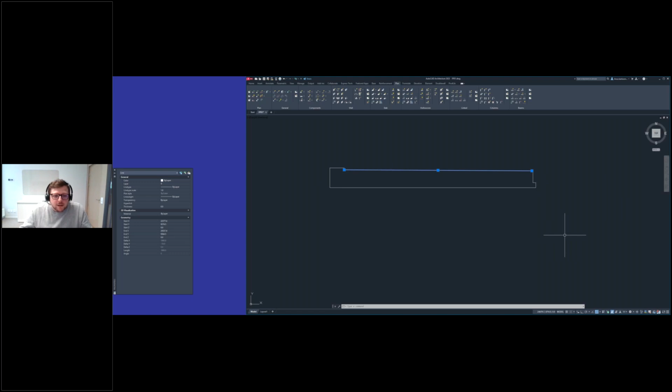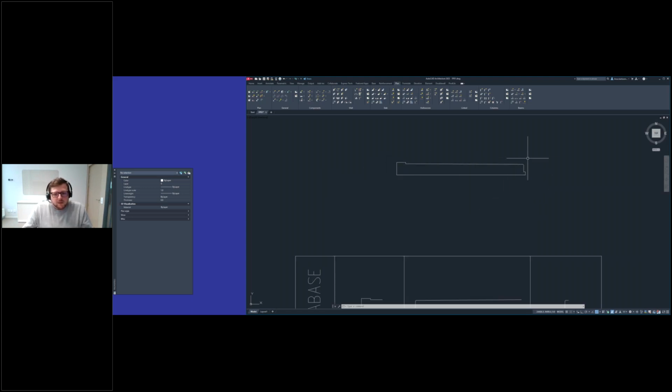To make sure that Impact knows that, we need to create individual end caps for each balcony type. For the same size, the depth or width, you can reuse the end caps. But if you have a building where some are 2 meters, some are 2.5 meters and so on, then you need to make individual end caps. It's pretty simple. Often you get some sort of cross section, or you have the measurements. Then you just need to draw it like I have done it here.